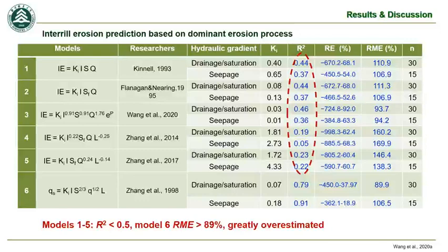In this study, the slope length was found to have a profound effect on the interior processes for different near-surface hydraulic gradients and rainfall intensities. However, the slope length factor was ignored in interior erosion predictions in former studies. This table presents the comparison of the existing interior erosion equations based on the data from this present study.